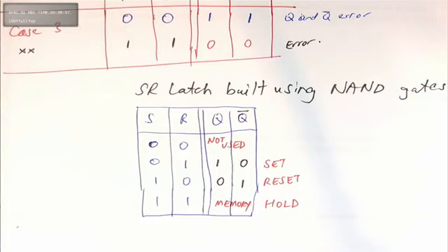So once again, when we have our latch, we deliberately make sure that for S and R, we never supply a 0 0. Your input sequence into your SR latch should never be a 0 0. Our design should be such. There should be a bit checker or some comparator checker. 0 1 will always give a stagnant answer. And if SR is 1 0, your Q, Q bar will be 0 1. That will always give a stagnant answer.